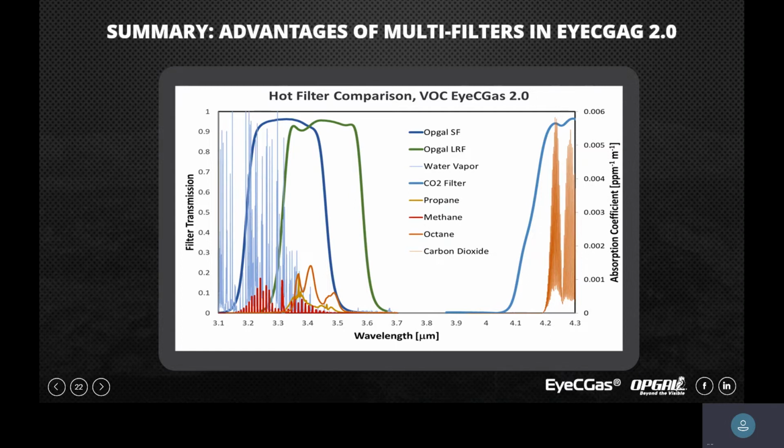And the CO2 line is sitting over here, on the edge of our detector. That's why we have a dedicated camera for CO2 and CO for sensitivity. But if we replace the filter and put a CO2 filter over here, we can see CO2 with diminished sensitivity, which for some applications is good enough.